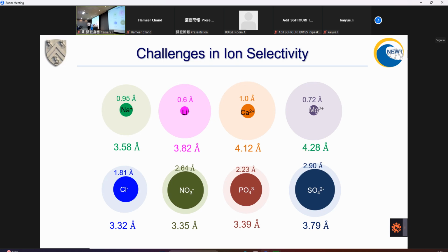You can see here in lithium recovery, one of the biggest challenges is actually separating lithium from sodium and potassium, and they have the same charge and very, very similar hydrated ion radius as well. Another challenge is to separate the monovalent from divalent, just because of the scale formation issues, and also in lithium separation, the precipitation of this divalent cation is one of the reasons that leads to very high loss of lithium. I won't have time to talk about the lithium sodium and lithium carbonate calcium separation today, but we've been actively working in this space.